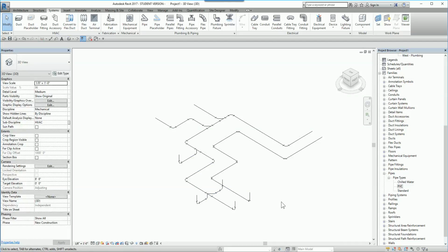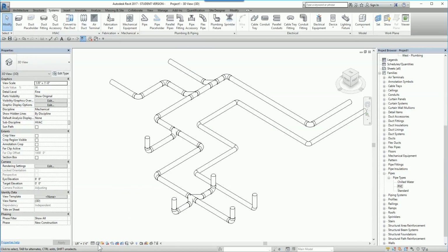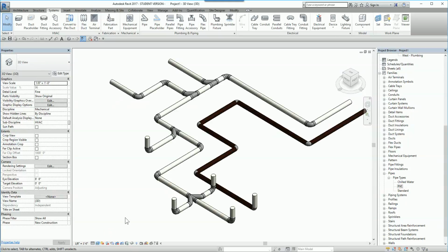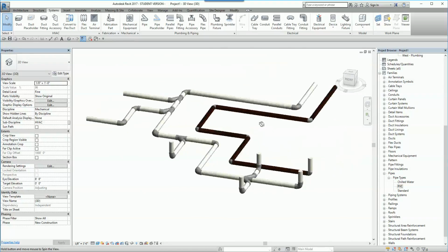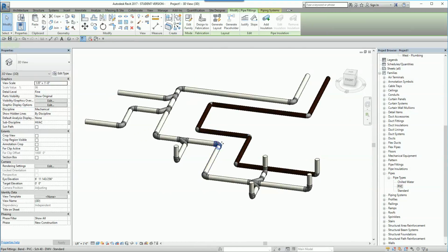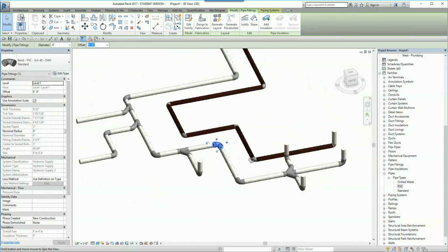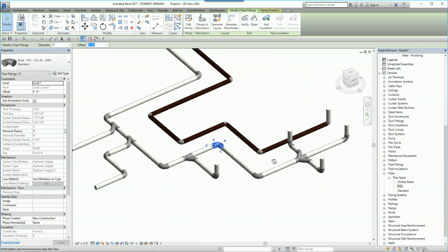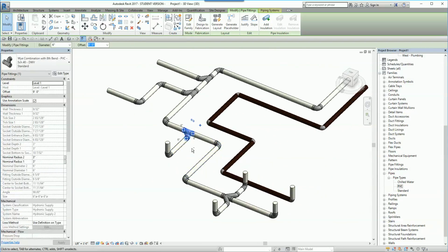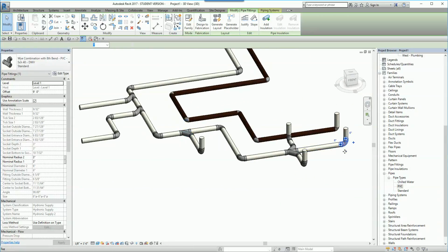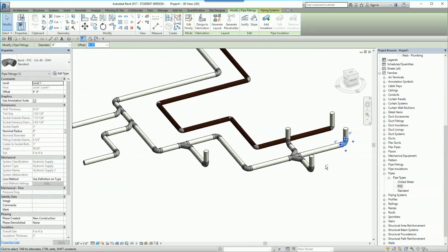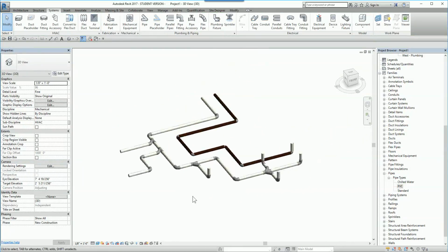So now we go to our default 3D view. By default, the first 3D view is shown on a very low detail level. So for that, we either do fine, as you can see. You can even change the resolution of it to realistic, and you can see the different types. And when you press your scroll wheel and press the shift key, you will see that you can rotate anything. Now when you're selecting an object and do the same shift and wheel mouse, it will use that as an orbit point. If I select this one, you'll notice it will do that around that, and if I select this guy here, it's going to rotate around that.